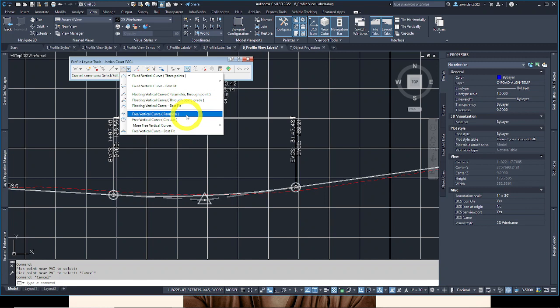This is usually the best one. They're not shaped like a circular object. They're usually shaped parabolic, and sometimes you can have a free vertical curve that's usually parabolic. It fits amongst points to go parabolic. There's an asymmetrical parabolic, so it has two different curves. Circular is just a little more round topped. It's not as advantageous of a geometry for profiles.